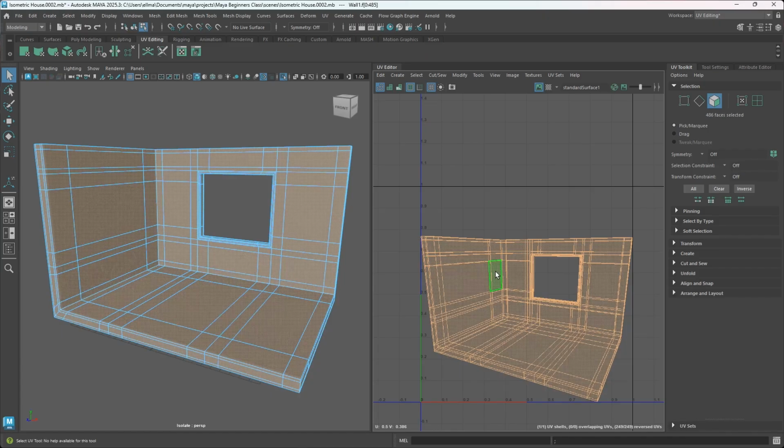Now the next thing for us to do is to select the edges, or the places where we want to cut. Now this is going to be a little bit tricky. That's why most times it is good to start UV mapping with models you create yourself, because trying to learn UV mapping with a model someone else created is going to be a little bit difficult and frustrating. You know how you create your model, the places where you have edges and the places that are rounded. So it really depends on you, not on the person who created that particular model.